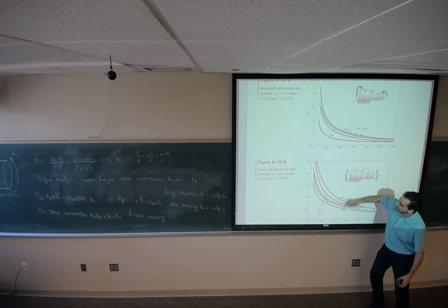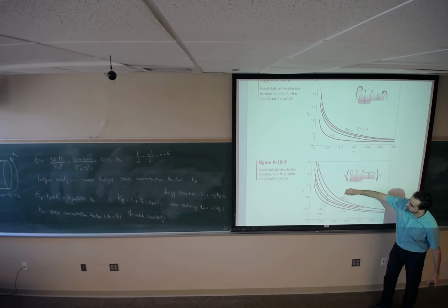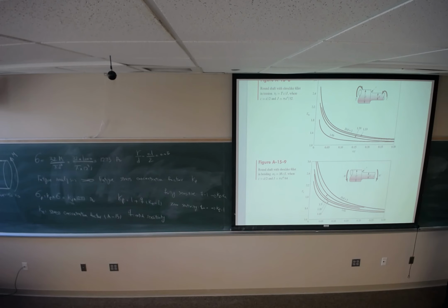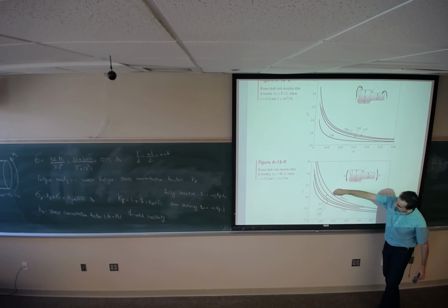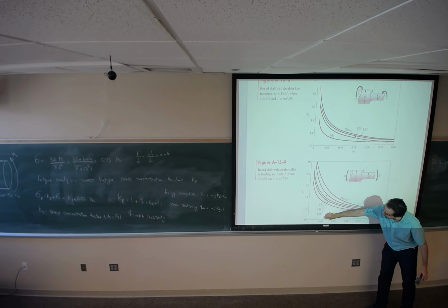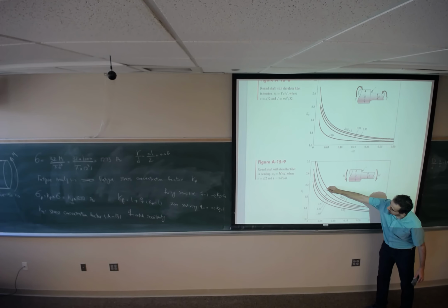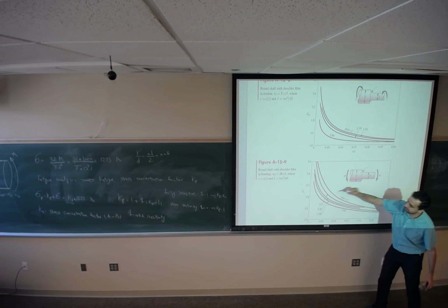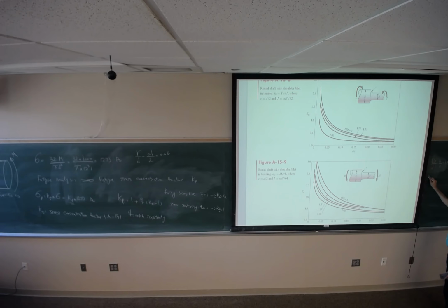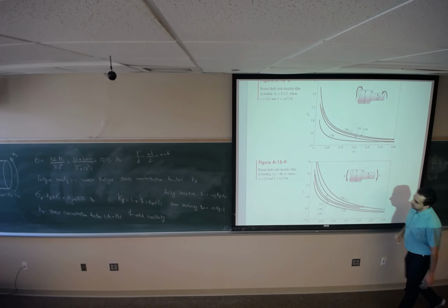So now, depending on the ratio between the uppercase D and the lowercase d, I can find the KT. 3 divided by 2 is going to be 1.5. It's going to be this line. So 0.05 goes up somewhere here. 1.8, 2.2, about 2. I read KT as a 2.